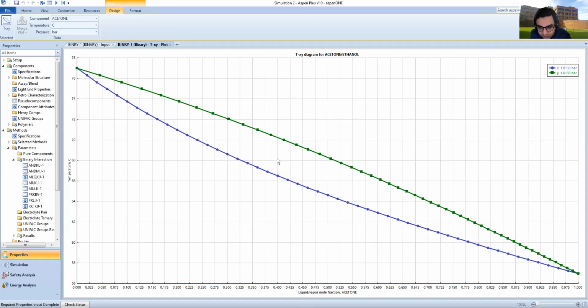And I need to find the point in this envelope. I need to find the point along this line where the distance on the left-hand side represents the vapor, and the distance on the right-hand side represents the liquid. I need to find the distance where basically it's 20% vapor and 80% liquid, right? So the distance from the 0.4 line to the blue curve should be a quarter of the distance between the 0.4 line and the green curve. And I think you've done this in mass transfer by this point in the course.